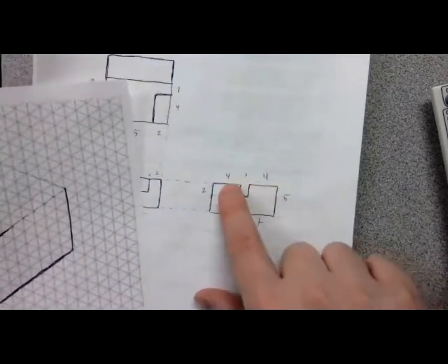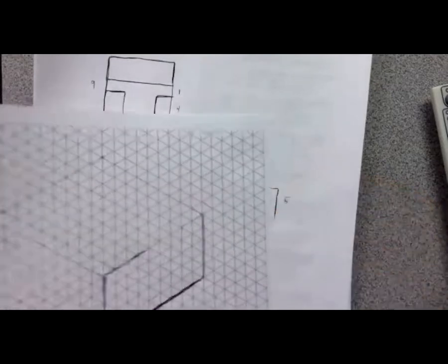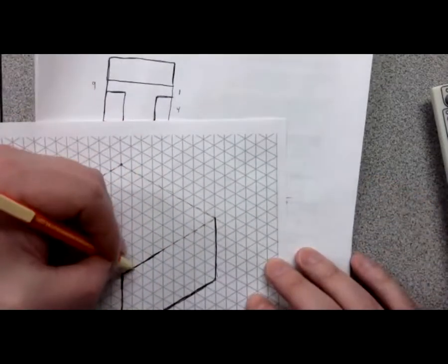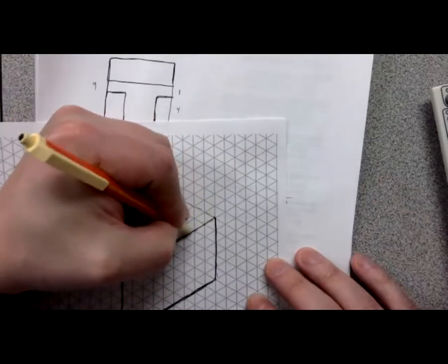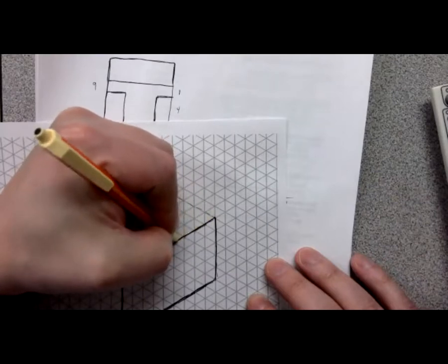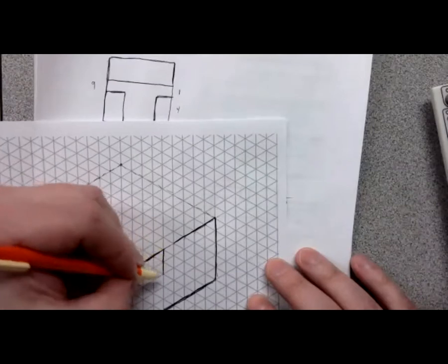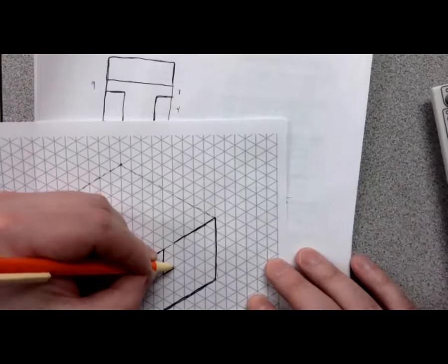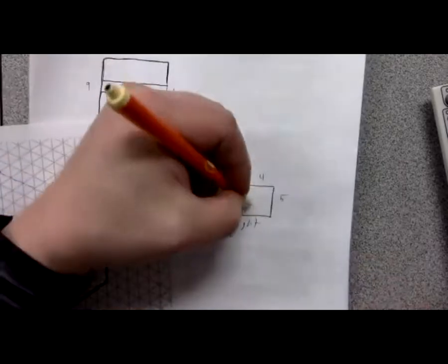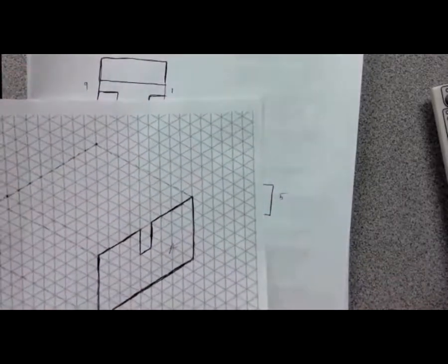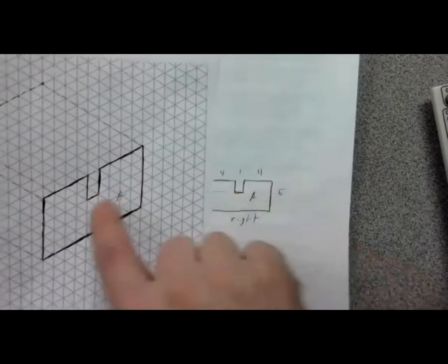And then the only hard ones across the top here, I've got 4, 1, 4. I've got a gap in between there. It's 2D. So I've got one line here for 4, another line over here, 1, 2, 3, excuse me, 4. And I've got this gap here. It's going to go down 1, 2, go over 1, go back up 1, 2. So again, if you want to label your faces, if we call this face A, that's my right face. That's what I'm seeing right here.